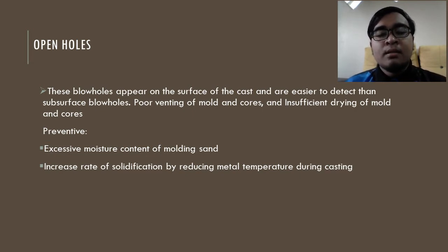How do we prevent it? First, avoid excessive moisture content of molding sands. Second, increase the rate of solidification by reducing metal temperature during casting.